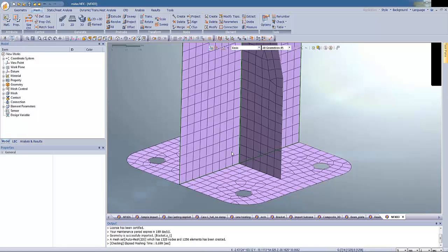So this last option, which I didn't mention today, provides manual extraction, and it enables you to create mixed surfaces between suitably selected pairs of solid bodies. So once again, thanks to this command, you will be able to create lighter models more effectively. Lighter means in some cases you will use shell elements instead of solids, and this will lead you to obtain shorter analysis times with an acceptable level of accuracy. And now let's go back to the presentation.